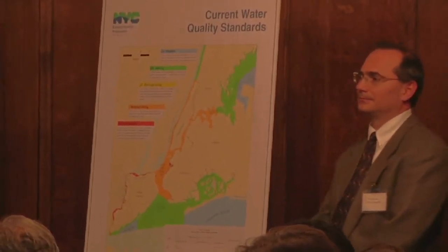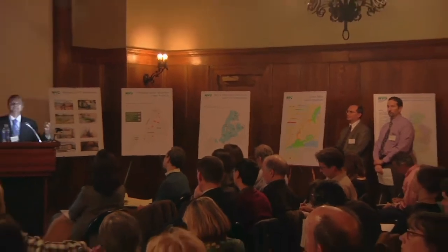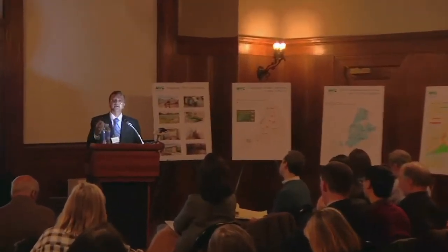But we have developed an empirical methodology. Tom worked on characterizing the different types of litter that we get typically from land uses, and then using their floating characteristics. Because as part of one of our permit requirements, we need to report on what our floatable control measures do, either a net around the outfall that is capturing all of those, what kind of retention or removal rate we achieve. We have been doing some empirical modeling of that, but in terms of blockage, they generally tend to clog the catch basin, but once they get into the system, they have enough velocity to get carried to the treatment plant.